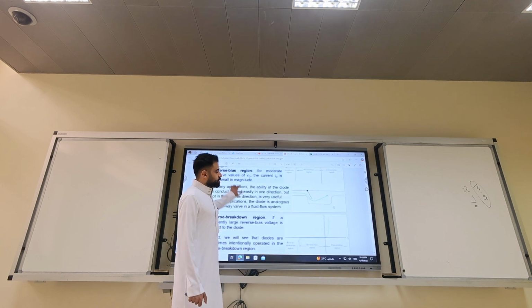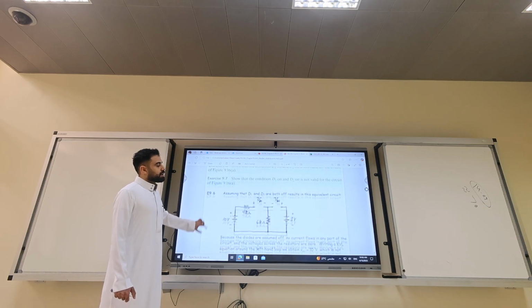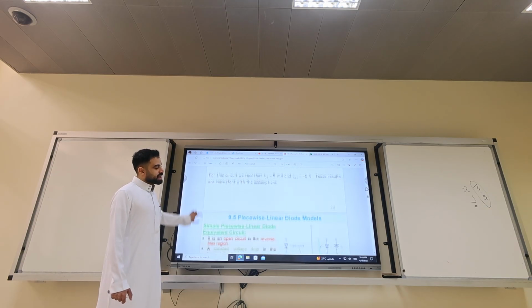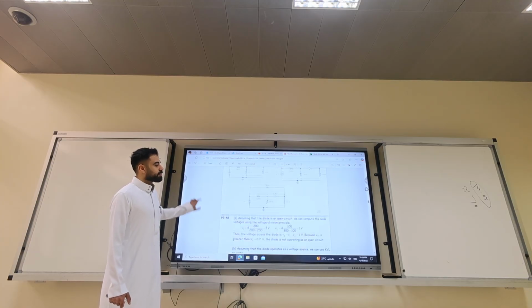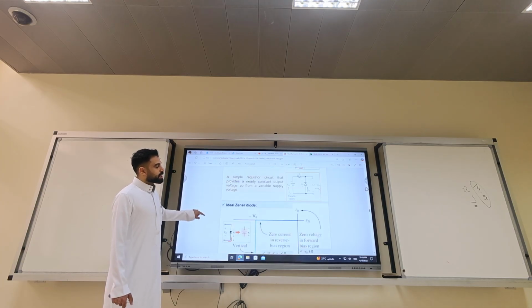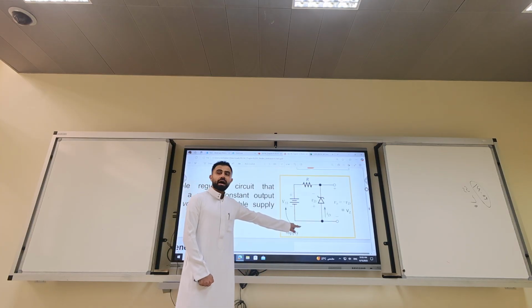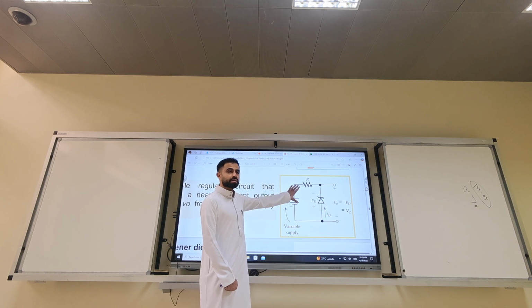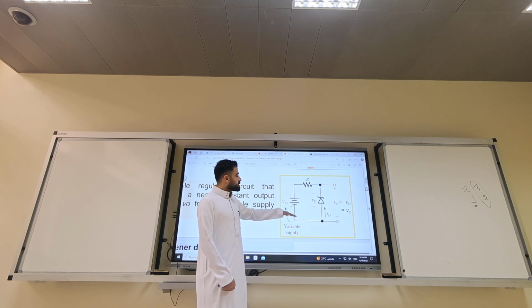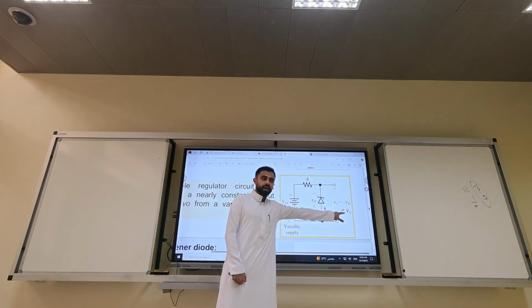So last time, we talked about the Zener diode. I made a mistake, not a mistake, but somehow a not good visualization of the problem. So remember the regulator circuit? It says here variable supply. This is a variable DC supply. So always the voltage here is positive. If the voltage is 0.1, what's the output? VZ.